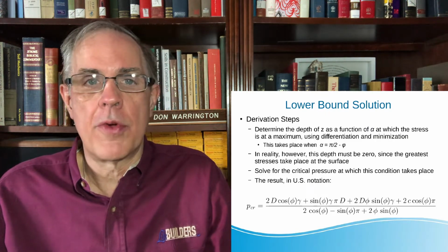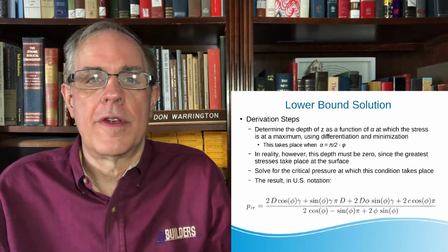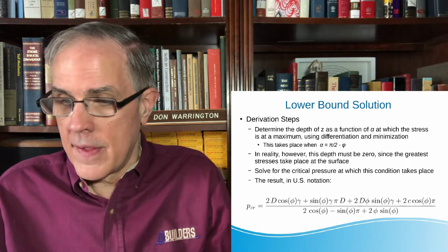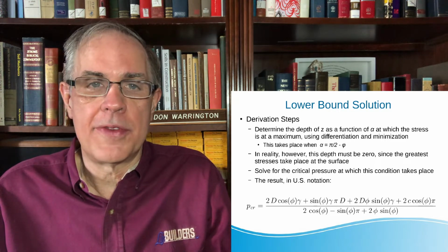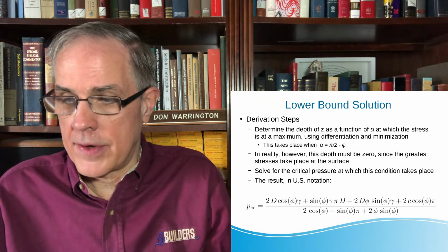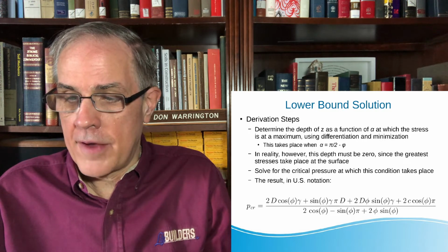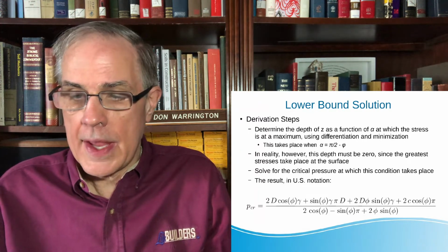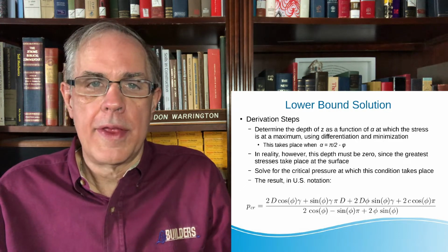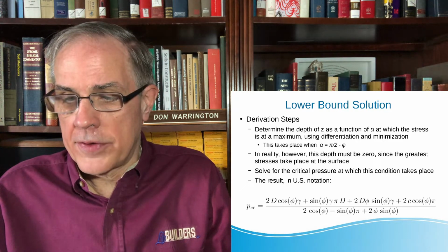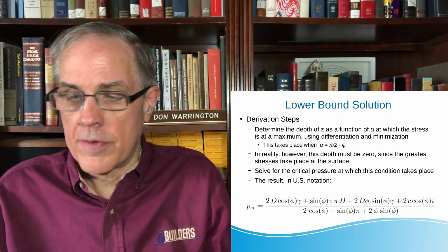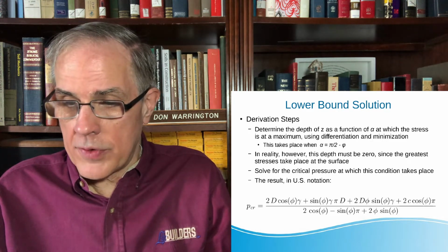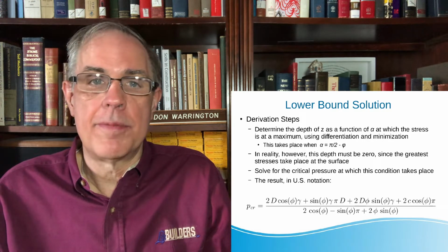At this point, I'm just going to walk you through the derivation. I have a more complete derivation on my website. We determine the depth z, in other words the depth below the foundation, as a function of alpha at which the stress is at a maximum. And we can show that alpha, at which it takes the maximum, is pi over 2 minus phi. In reality, however, the depth must be 0.